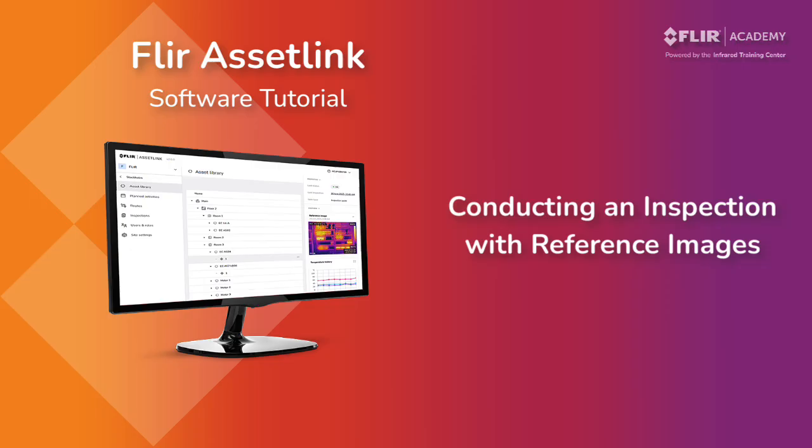Reference images are used by thermographers during an infrared inspection to help them confirm if they are saving data correctly. These images provide the right orientation and the proper perspective that operators use to ensure consistency when capturing an inspection point. This is important for programs that are using thermal imaging for data trending and analysis.